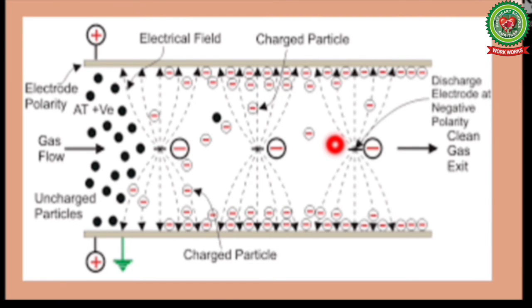With the help of this image, we can understand the working principle of ESP. When a high voltage current is applied across the two plates or electrodes, the negatively charged plate attracts the dust particles, which further attracted by the positively charged electrode by the process of ionization. It makes the suspended particle move toward the collector electrode and deposit on the electrode surface. The collector electrode is washed periodically to remove the impurities.